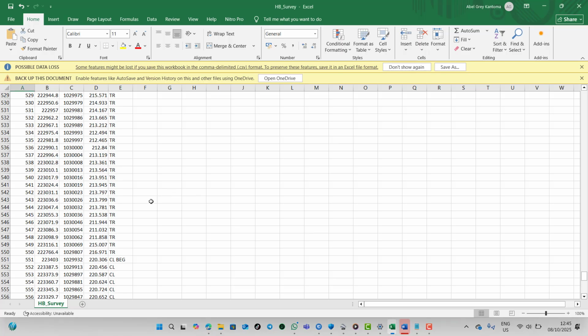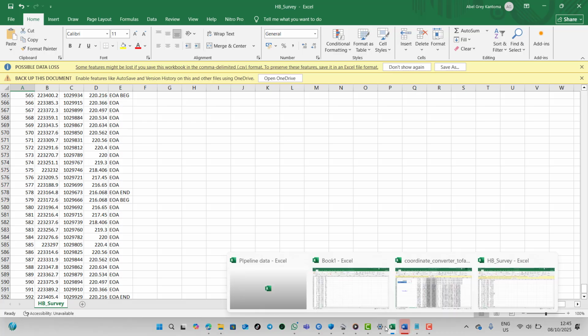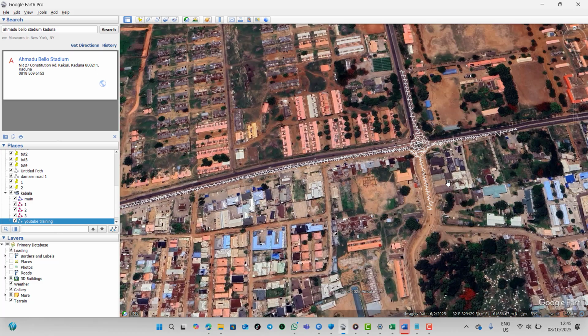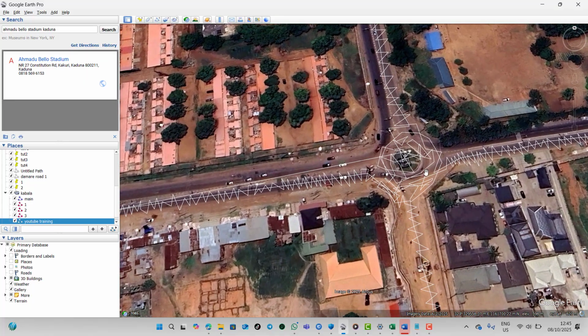So we have spoken about the three center line, edge of asphalt, like I explained earlier. You have some edge of asphalt, which is this. For example, if you are designing this road, we must find a way to connect it with the edge of asphalt here. Very important, so that you won't have this 1 meter above this particular existing road.